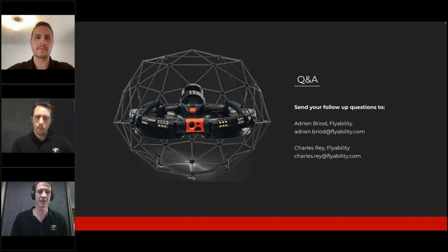That's where you'll get a ground sampling distance of about 0.2 millimeter per pixel. It doesn't mean you won't see a crack that's smaller than 0.2 millimeter, since you'll still see contrast, especially if it's quite dark on maybe a clearer surface.